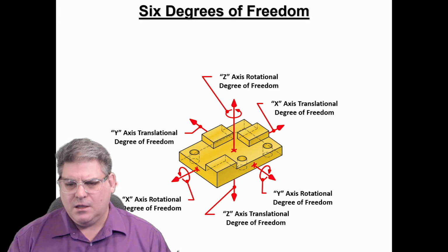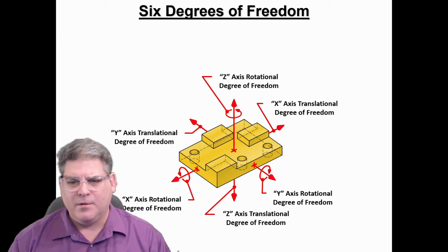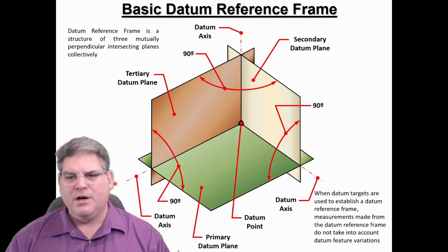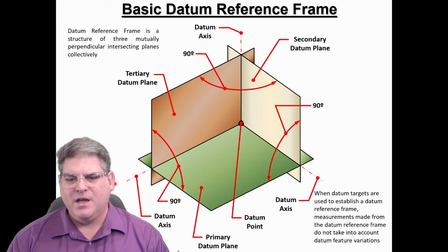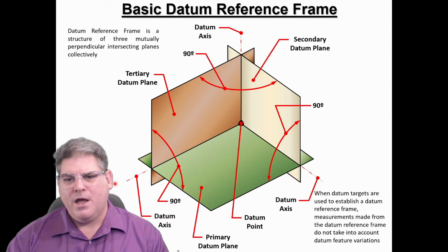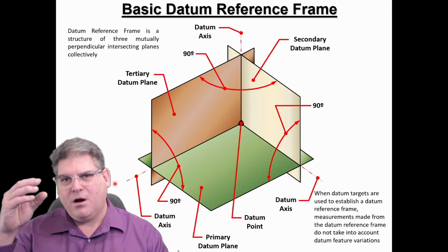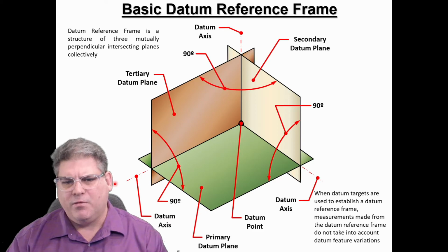And this is not an easy concept to get a hold of, but I think we can do a pretty good job of really defining what the heck is required. Okay, so here is the theoretical perfect fixture. So we have 3 planes in space, and they define the Z, the X, and the Y. And if you can imagine taking your part and dropping it in there, it's going to lock in and never move, right?